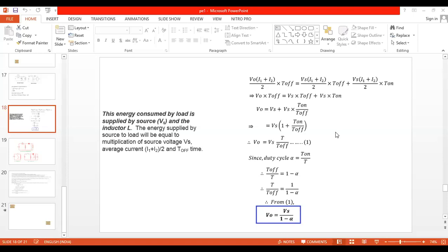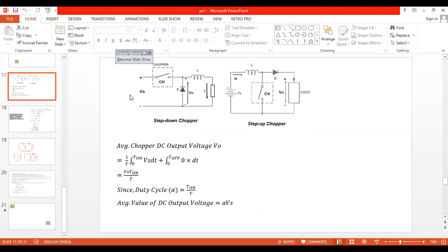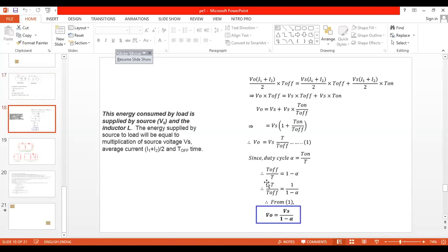This derivation you can see, I just mailed that one, the complete derivation, similar to the one we have taken for step up down chopper. So every student should be clear with these three formulas. Step down chopper derivation is this one. Step down chopper output voltage equals del into input voltage. Step up chopper, what is the expression? Output voltage equals 1 by 1 minus del into input voltage.